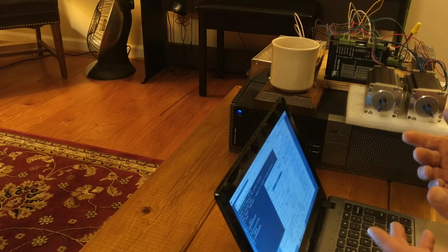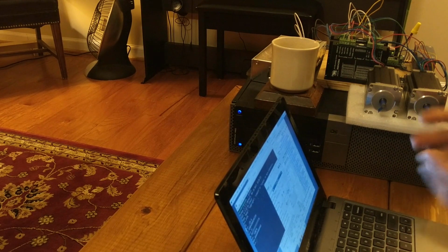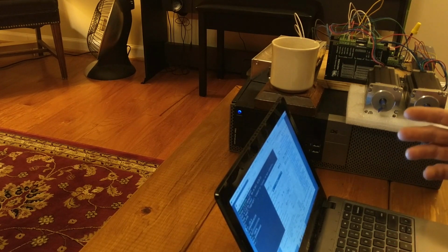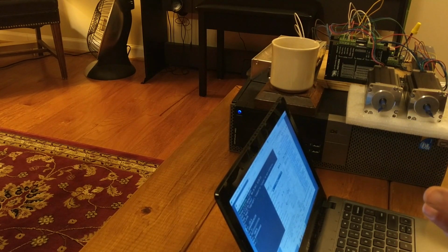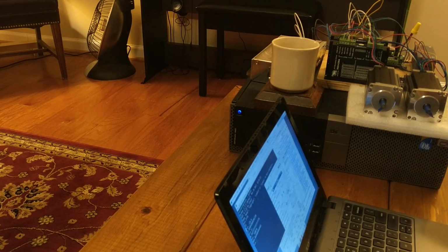Now the goal here is to test the full range of your machine by slowly increasing the range you're testing, and then by also playing with different velocity and acceleration values to see how fast you can go and how far you can go while still getting performance consistently out of your machine. You don't want it to rack up, you don't want it to stall, any of that, to see what you can get out of it without anything acting wonky, basically.